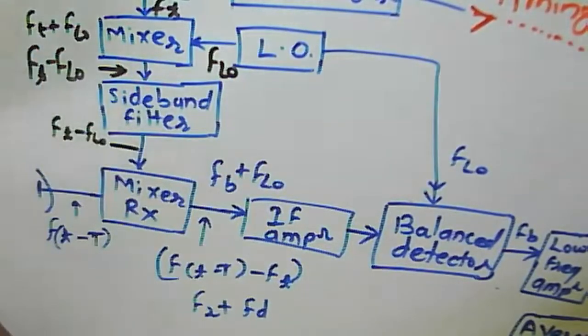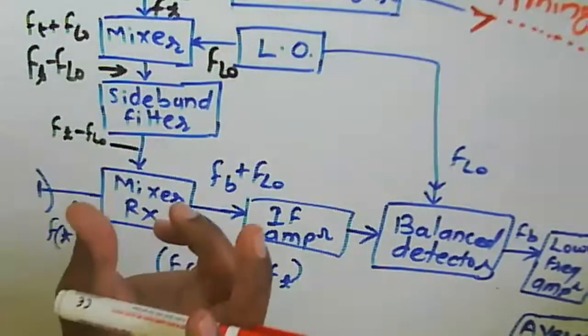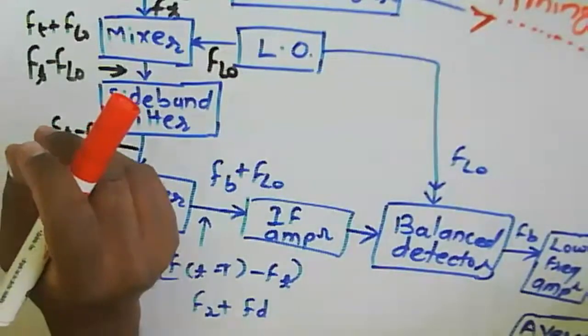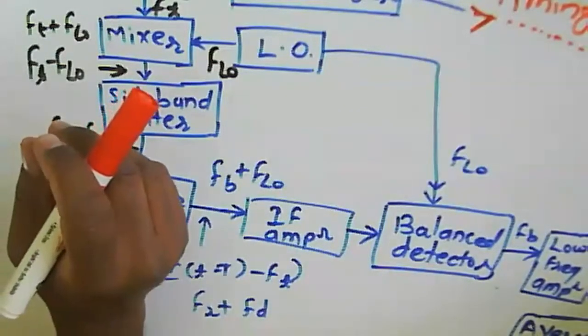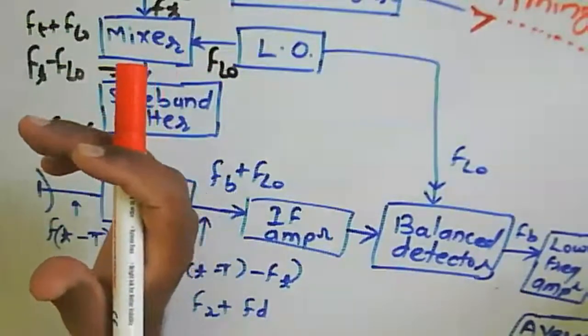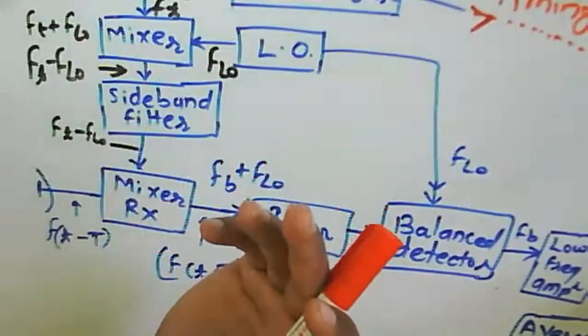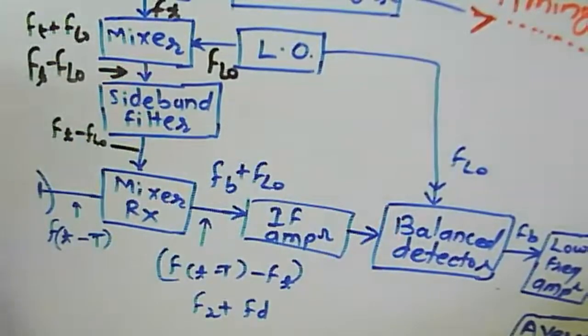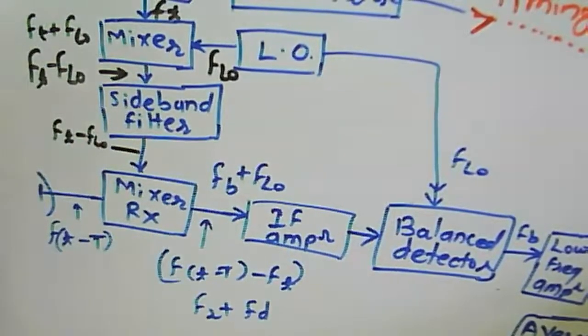So in that case we need to reduce the error. An accurate range has to be measured by the device, and the signal to noise ratio at that particular beat frequency signal is to be measured here.